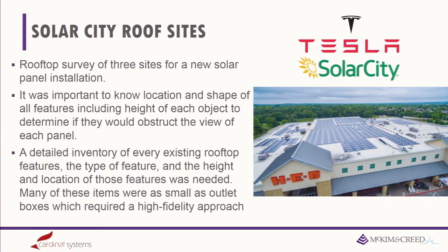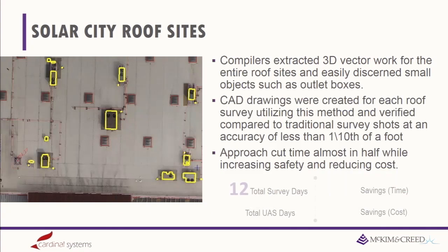We still do these rooftop surveys for Tesla. A lot of large box stores are actually putting solar panel installations on them, and they need to know where everything is on that roof. They need to know where all the rooftop units are, the parapet walls, all the existing pipes, the little electrical boxes that run the RTUs. So it's important that they have a survey of all this information so they can design where they're going to put their solar panels. So we flew 3 locations